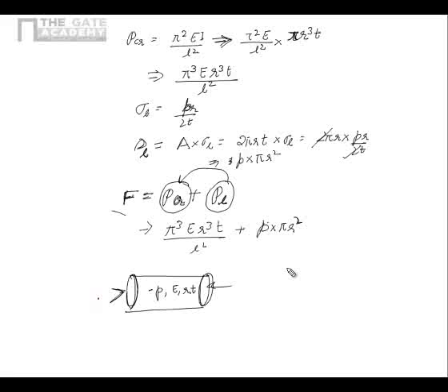So in this case, it becomes again a very interesting case. Now in this case, what happens is that sigma L is minus PR upon 2T, because now it's a negative pressure, which means there is a suction happening.